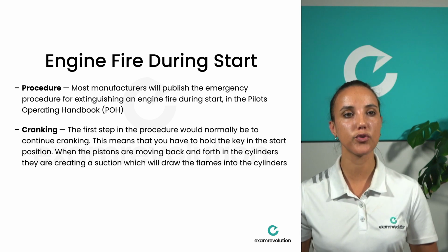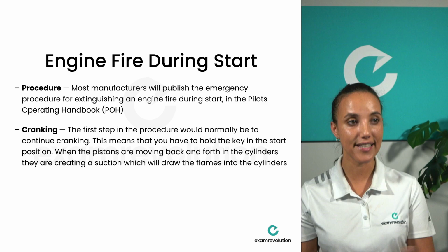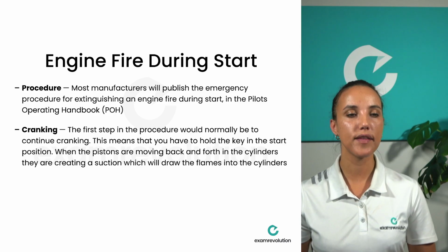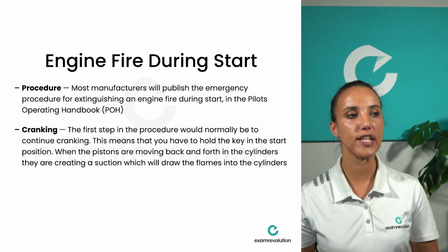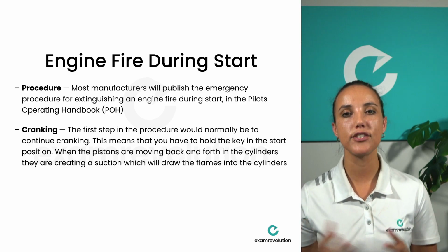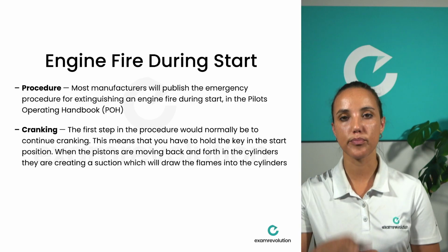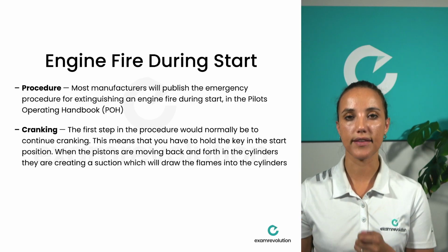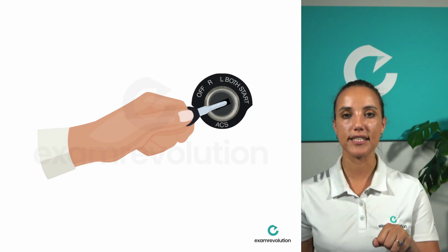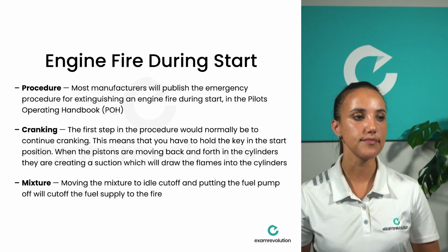So the first procedure would normally be to continue cranking, and this means that you have to hold the key in the start position. When the pistons are moving back and forth in the cylinders, they are creating a suction that will draw the flames into the cylinders. So the starter turns over the engine, and this creates the suction that we require. So once again, keep the key in the start position while you are doing all your other checks to make sure that you extinguish the fire.